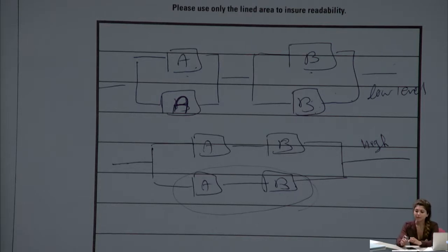One of the major challenges when you think about redundancy is the weight of the product, because weight is always going to be one of the contradictory factors with the speed or other performance characteristics of any mechanical system. So when you want to consider redundancy, you don't just throw in as much redundancy as possible. You have to find the really critical components whose failure is going to make the whole system dysfunctional.